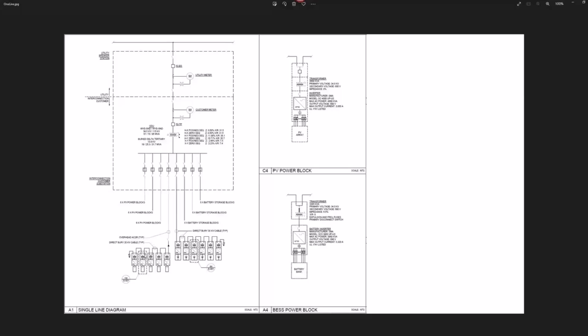And at the very end of this collector cable system, you have the pad mount transformer. Some people call them GSU. Again, different people have different preferences of terminology, which connects the inverter usually at 0.69 kV or 0.6 kV up to 34.5 kV.